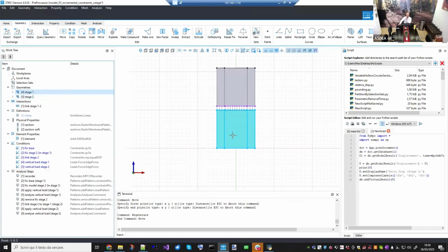Let's say this one is the first wall, and I do an analysis. This wall deforms due to a certain weight. And then in a second stage, I will build another piece of wall on top of that one on the deformed configuration. Now, the problem is that when you build your CAD model, you don't know what will be the deformed configuration. So you are actually modeling this one in the undeformed configuration, okay?